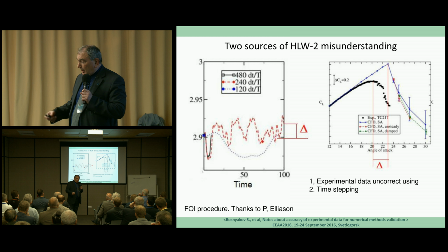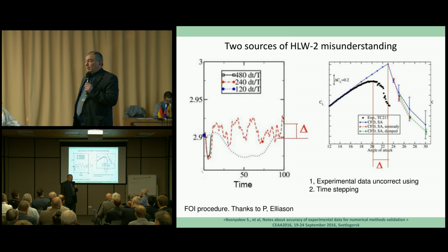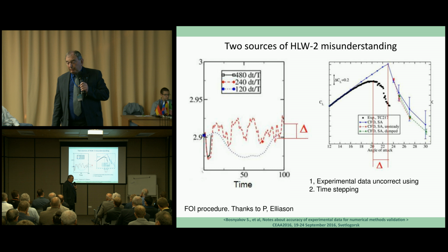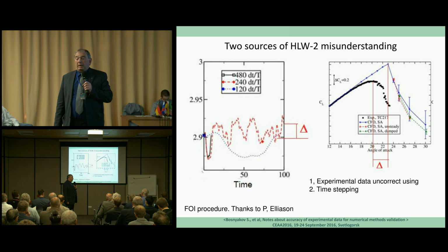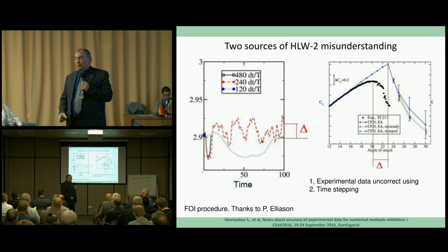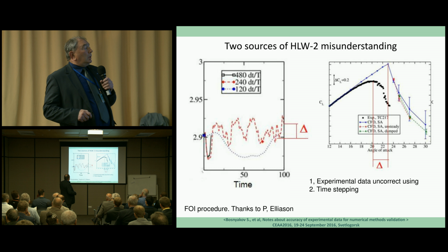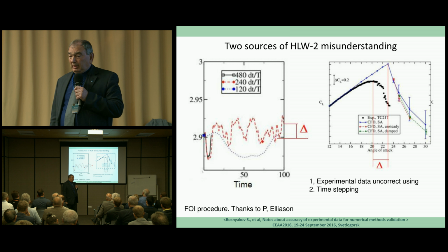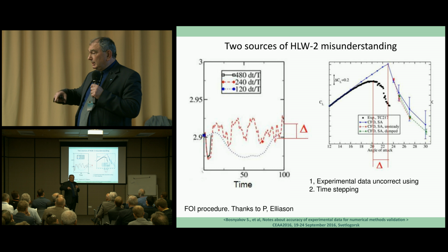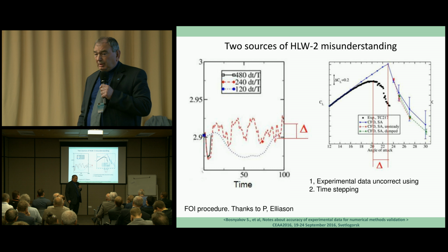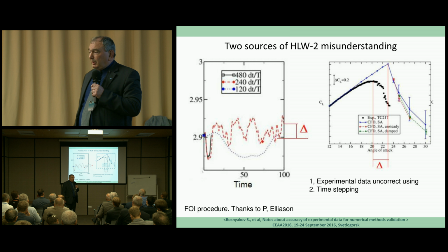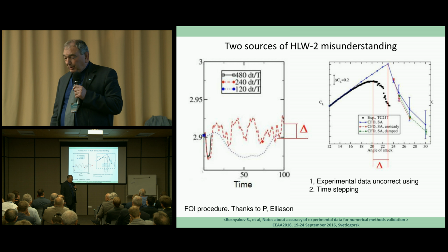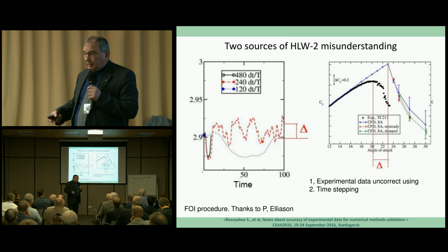But what's to do with unsteady, or so-called URANS? We discussed this problem quite carefully, and as a result we formulated and documented the so-called FOI procedure. It's an official procedure now. When you run with URANS, it's necessary to organize at least 3 different time-dependent procedures, and in the case of agreement of these 3 results, including spectrum, maximum, minimum positions, it's possible to say that you have a real URANS solution. Otherwise, you just study the behavior of so-called residual non-physical behavior during the stabilization procedure.